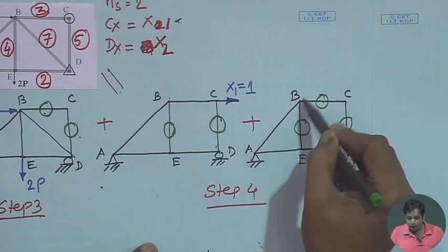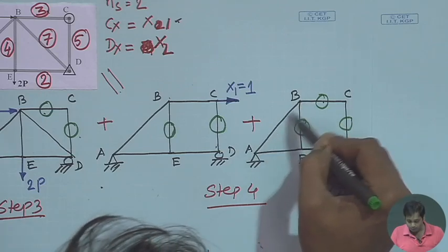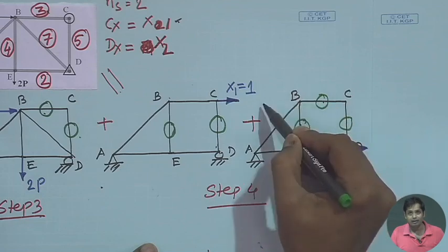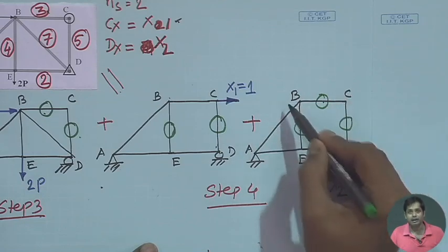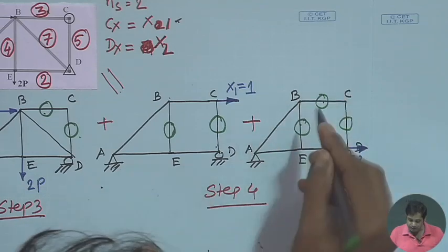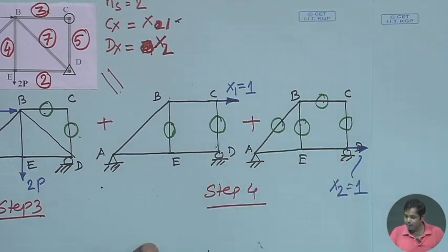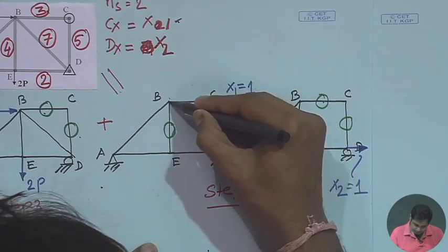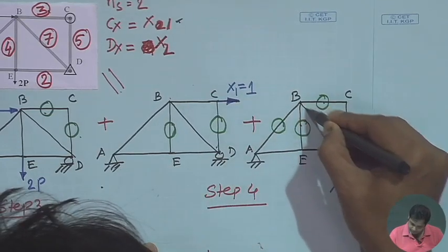So, there will be a component. The force in member AB has a component in the vertical direction and the horizontal direction, but no other forces at B can balance those components. So, member force in AB will be a zero force member. One thing I missed here: there is a member here as well.